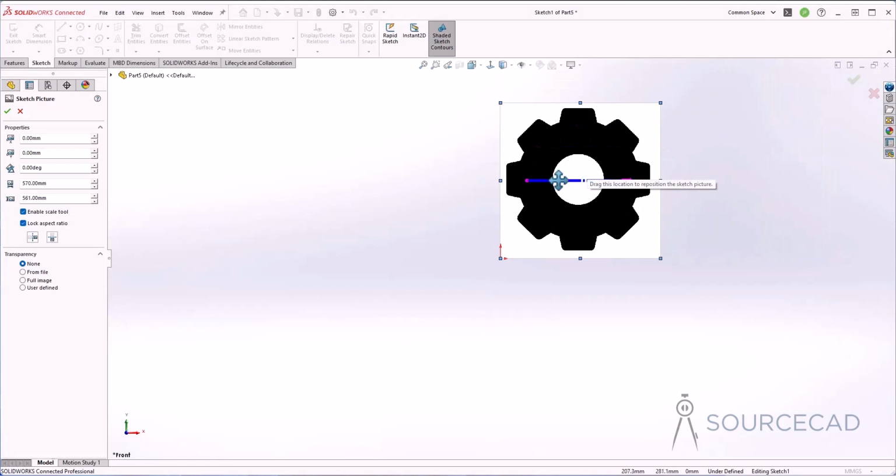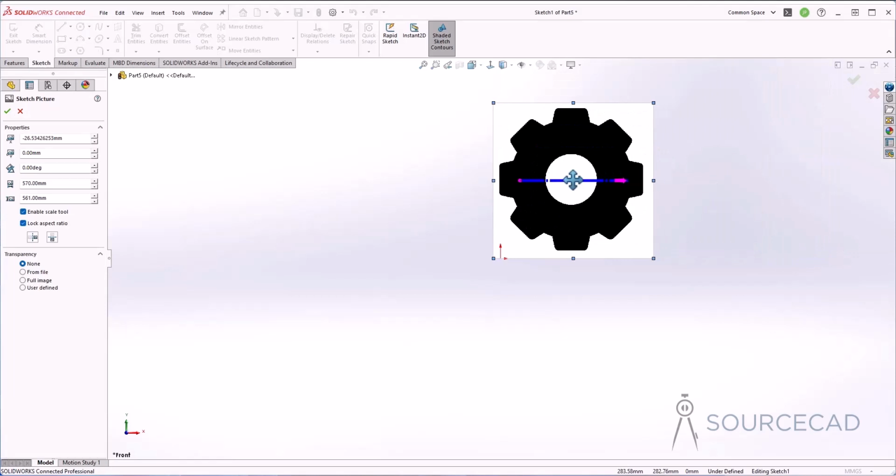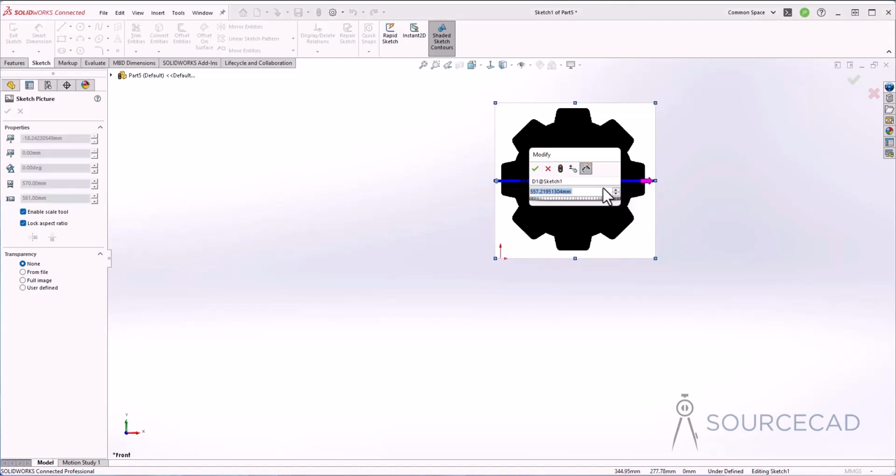Now, as you can see, the image size is not quite right. So I'll just make it right by moving this scale line. I'll just move it right here, and from here, I'll just move it right here. Now this length should be 200 units, 200 mm in this case. So I'll just type 200 and OK.